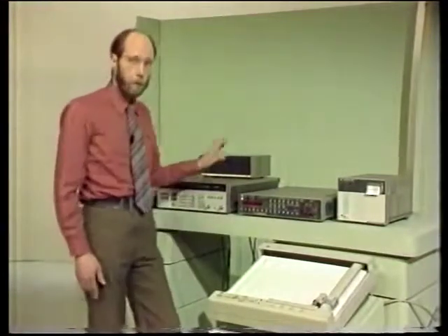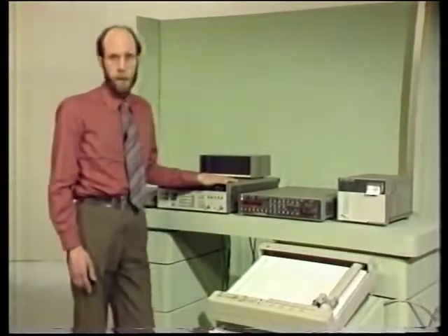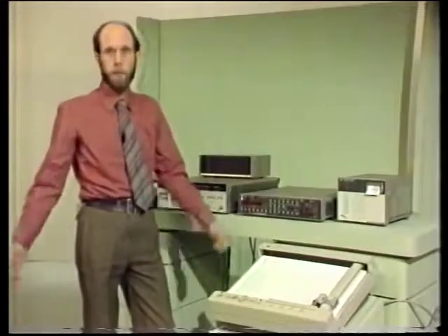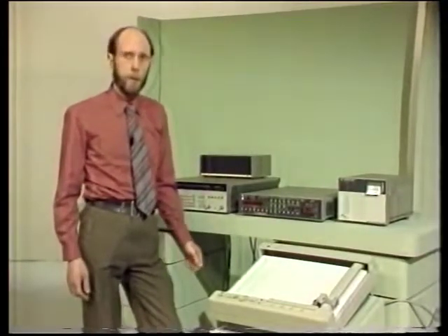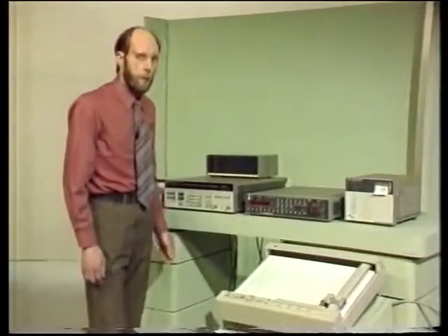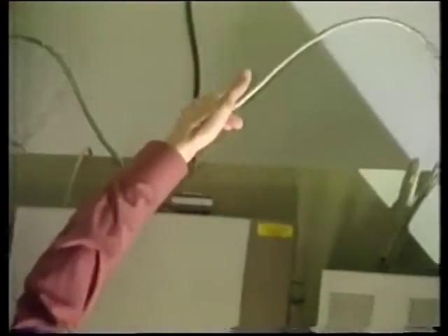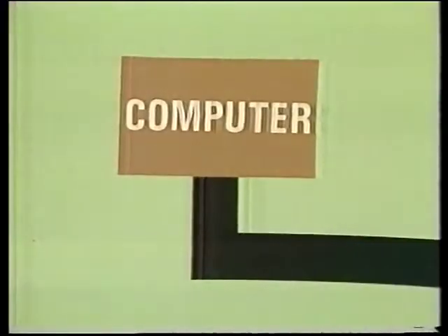You've seen this done automatically before, but the great thing here is that all these instruments are off the shelf with no special interfaces. So it's a simple job to unhook, say, the DVM and plug it into another totally different system tomorrow. As long as we work within this standard, there are no messy interface problems to worry about, and we have a completely flexible system. Another feature you'll notice is that each instrument isn't connected by a separate cable to the computer, as with Nick's star system. There is just one cable run linking them all together. So this gives a parallel bus structure, which diagrammatically looks like this.